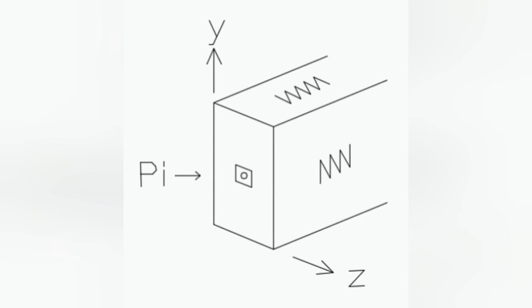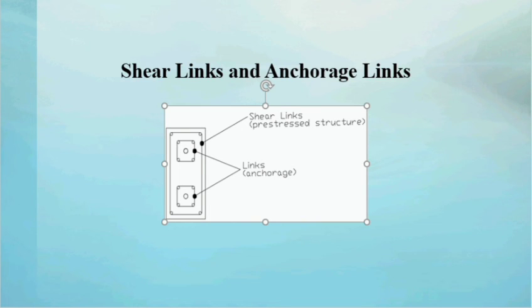Therefore, we can conclude that if the cables are arranged more toward the center of the vertical axis of the anchorage view, the split will be in a perpendicular direction to the axis, and vice versa. Reinforcement links must consider the bigger forces in the Z or Y plane.